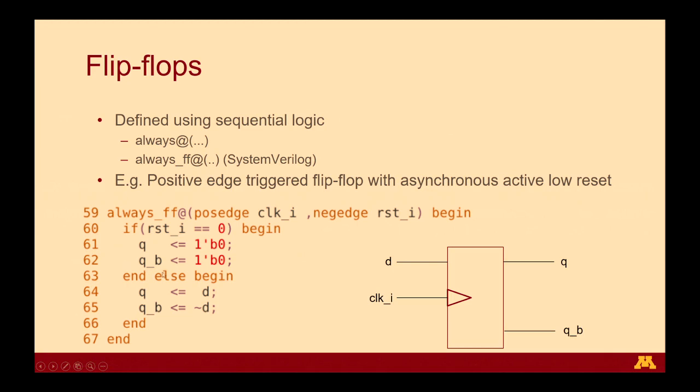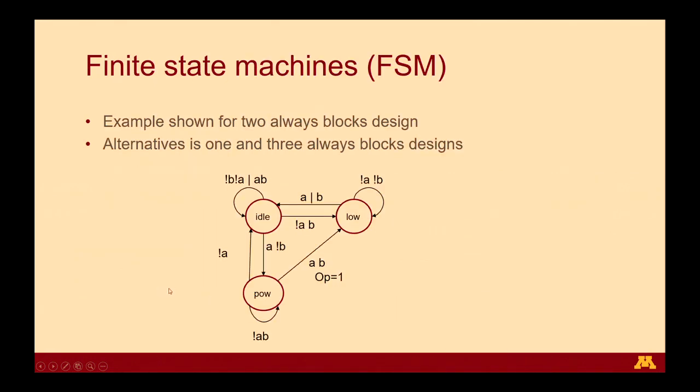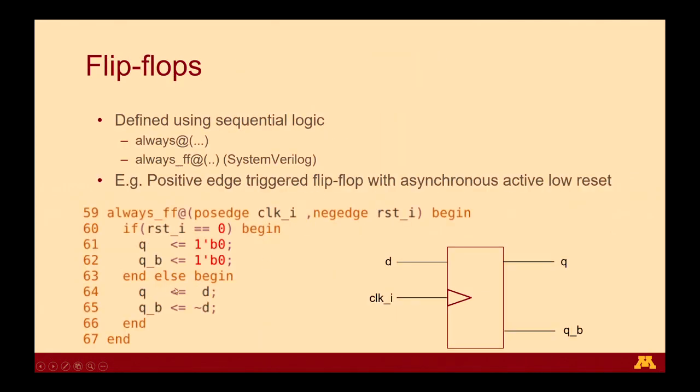The first line is the reset condition, where when the reset is, in this case, active low, we define the desired outputs. And when it is not in reset, as I mentioned before, the non-blocking operator mimics the flip-flop operation. Ultimately, when the synthesis tool looks at this code, it interprets it as a flip-flop like this.